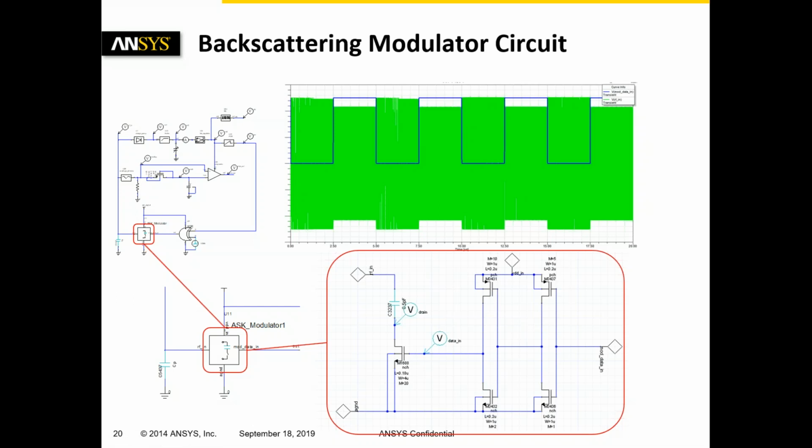The 4 transistors in the schematic in the modulator form a buffer to drive a switch that turns the capacitor either on or off. In the plot, the green curves are for the RF signal, whose magnitude is clearly modulated by the digital stream, blue.